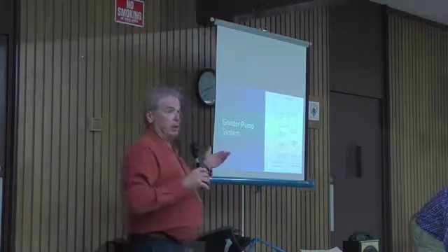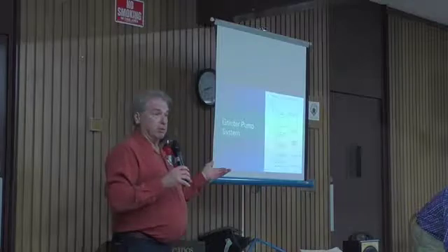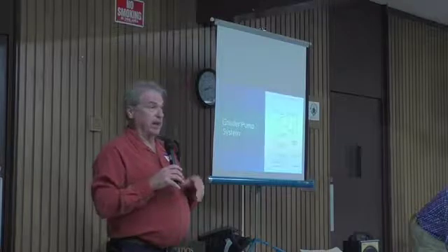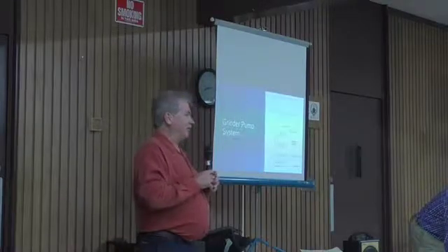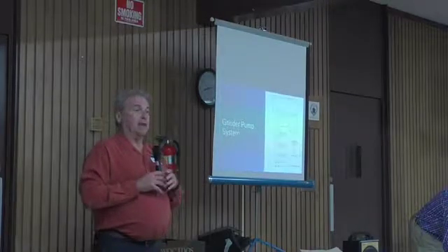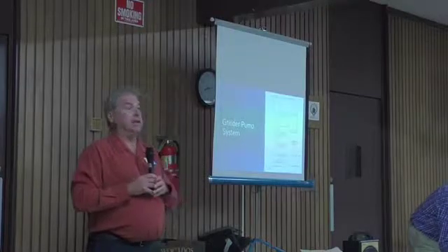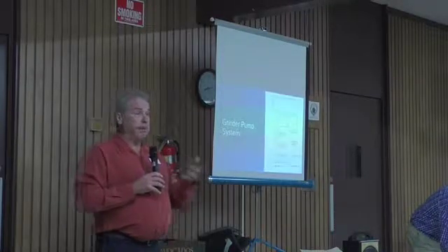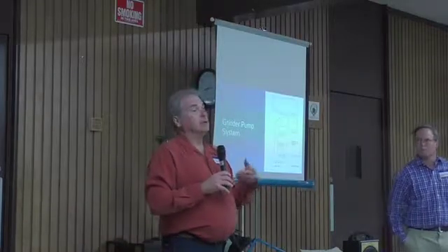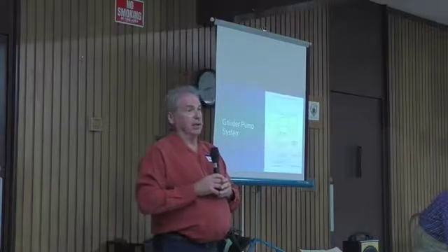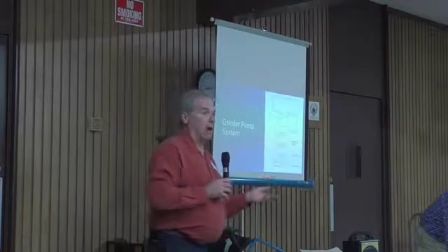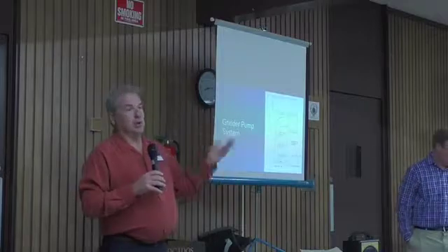So the arrangement that we would recommend, and what we've done with other projects, is that the district would own and operate those pump stations. And stop me if I'm speaking out of line, Val, for what you guys are assuming, but normally that's what would be done. As far as the electricity, it's not feasible to meter that electricity and have the district pay for it. So it would be the homeowner's electricity, but it's a very small amount of electricity, less than what a refrigerator takes, because these pumps only run a few minutes at a time, 20 times a day.